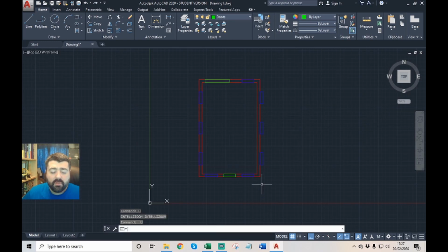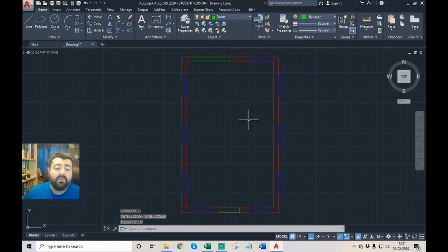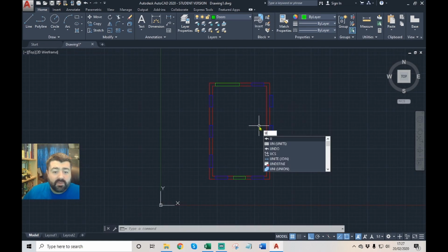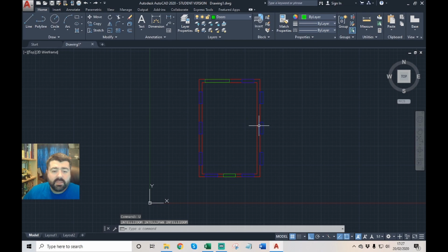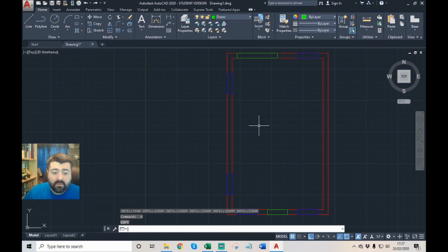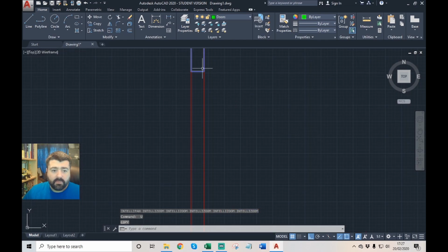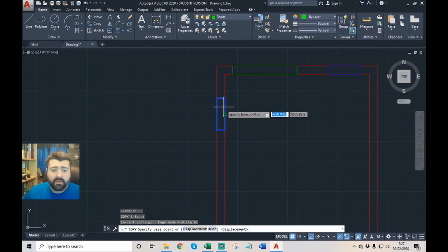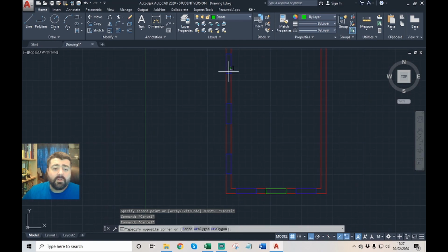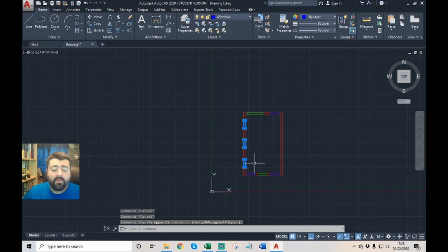So if I do undo, and then the other thing I forgot to mention earlier was if you do a command and then press space to complete it, pressing space again will repeat the same command. So I'll just scroll out and do something, and then if I hit the undo key, it's going to undo my scrolling. There we go, undo IntelliZoom. And if I hit it again, it's going to get rid of my windows, because that was the command before. If I hit it again, it's going to get rid of my middle window. There we go. So yeah, undo is quite a powerful command, and if you keep bashing it, you could just undo your whole drawing.